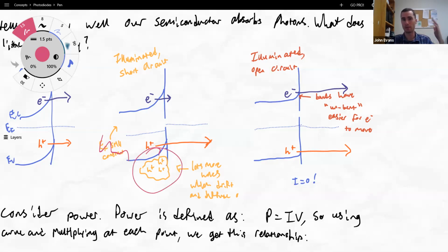So remember, the Fermi level tells you when there's like a 50-50 shot of finding one or the other. So if we've got like a whole bunch over here and say like a whole bunch over here, it starts out, the Fermi level is like, say, there. And then we're going to increase this. So now the Fermi level is going to come down right there. Okay. So that's what's going to happen there. So we're going to get this separation here. Now we're actually going to get a separation equal to VOC.